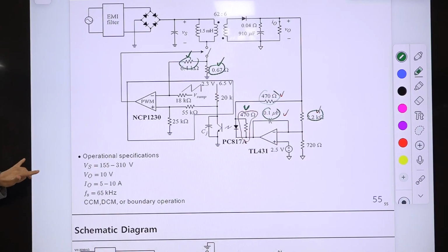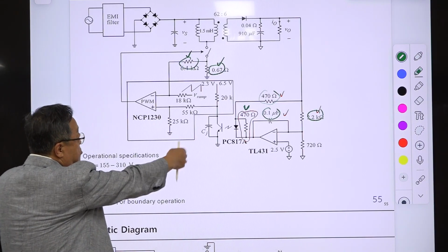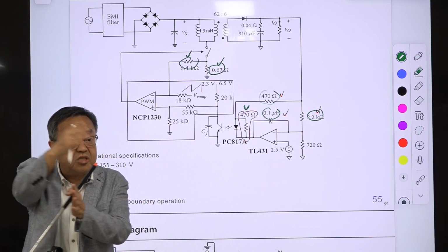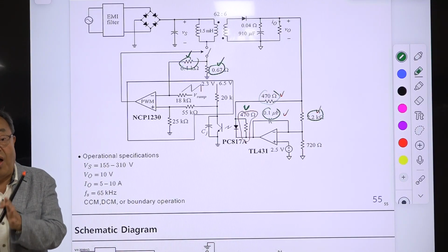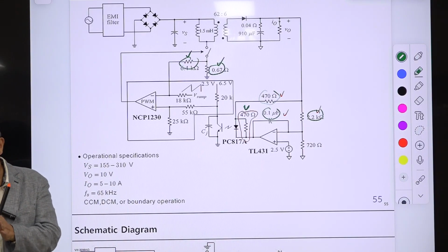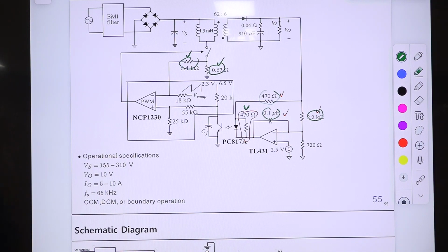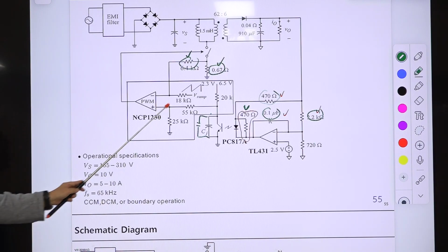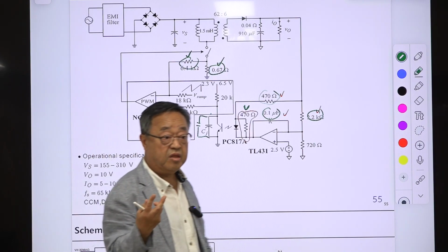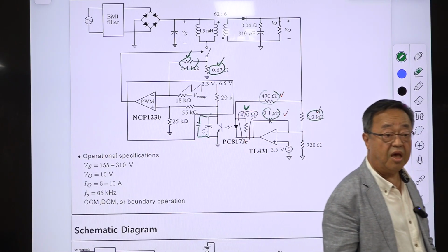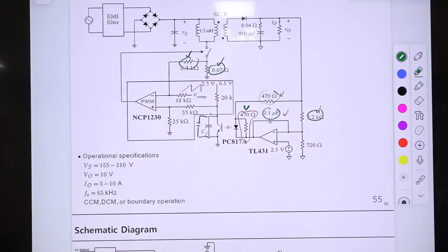Right? Then if the pole frequency calculated from your design is much higher than the one you selected as the minimum of 3 frequencies, what do you want to do? You add an external capacitor here, an additional one here. Okay? So parallel combination of this and this is used to determine the pole frequency at the desired location. Okay?